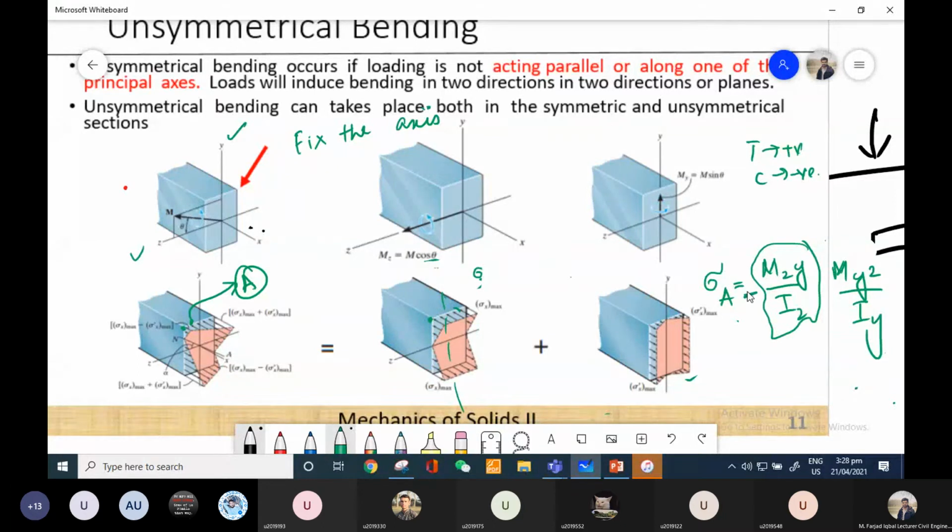And if you look into this second figure, due to this MY, I have in the second quadrant tension forces because the arrows are coming outwards. So I will say that there is a positive sign with this one. Now what I have done over here is made one generalized equation for all positive senses, right? My movement was acting in the quadrant where everything was positive. This y and this z axis, y was positive in the upward direction. Now I can fix my axis and I have one generalized equation.